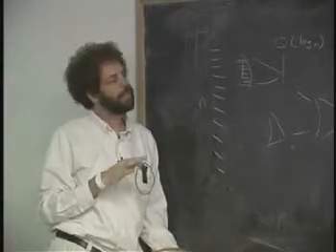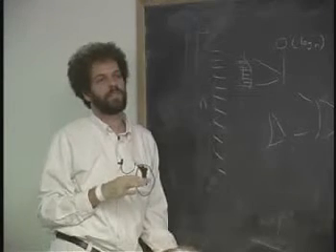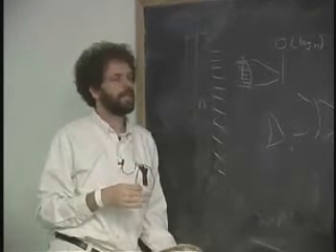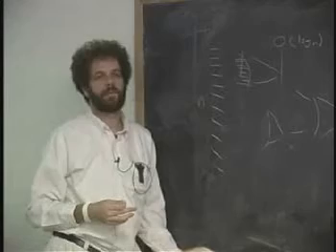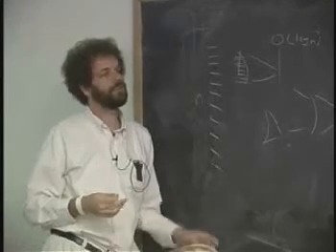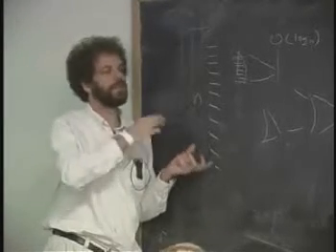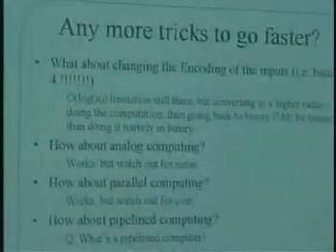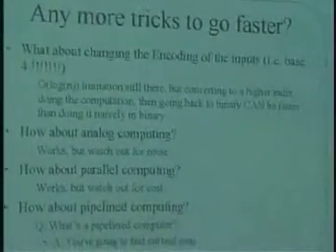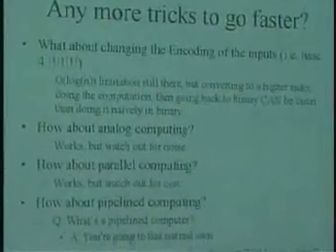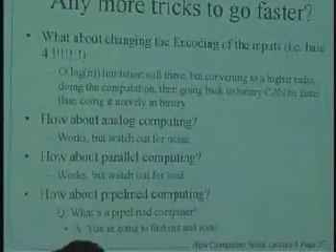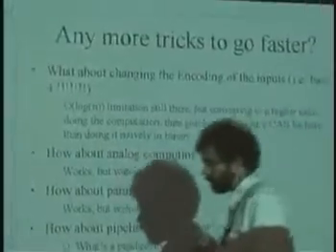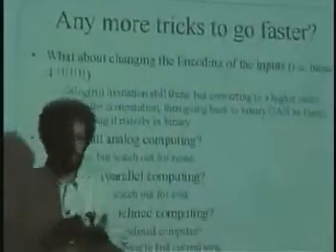But it turns out that n is usually not that big. 64, 128, it's not 10,000 bits. And so what that means is that usually the constant factors of the design will dominate what you in fact do. So it's basically order log n in theory, but in practice there are all kinds of tricks that you can do. I showed you the look-ahead of generate and propagate. There are also other tricks where you pre-process the inputs and change what base they're in.